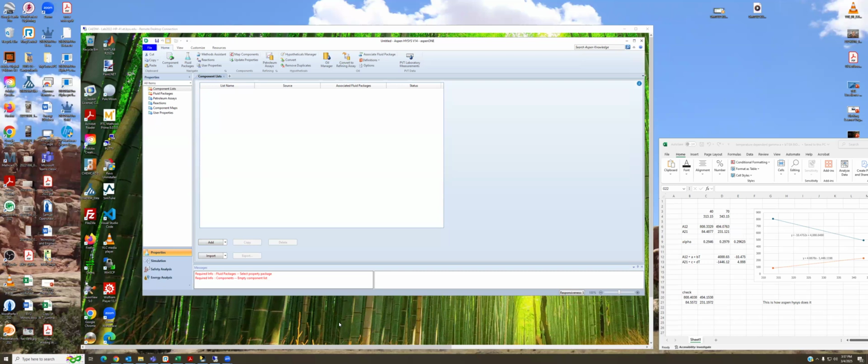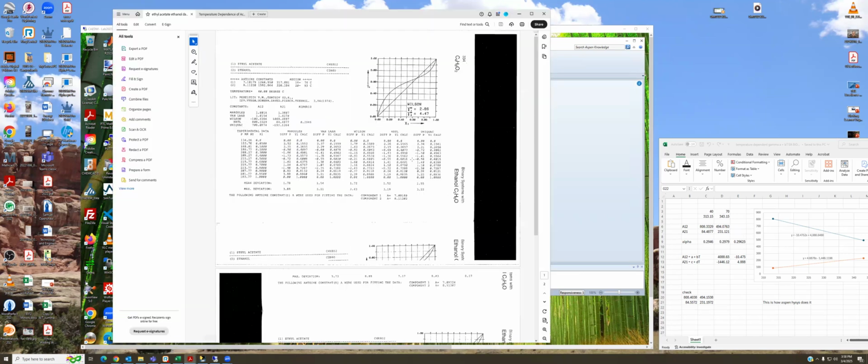This mixture forms a minimum boiling azeotrope, which presents a challenge for separation. But because the azeotropic composition shifts significantly as a function of pressure, we can potentially use a two-column sequence operating at different pressures to affect this separation. Let's look at some of the background information before we jump into the simulation itself.